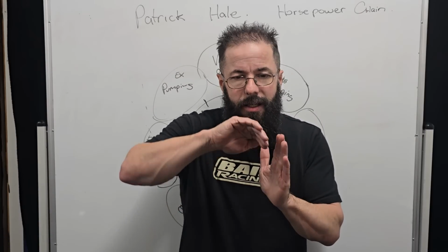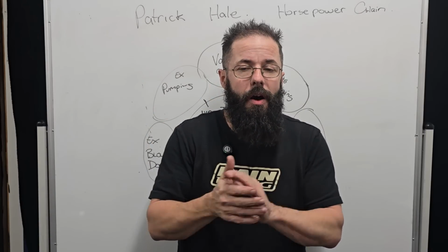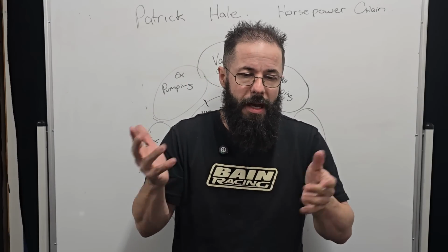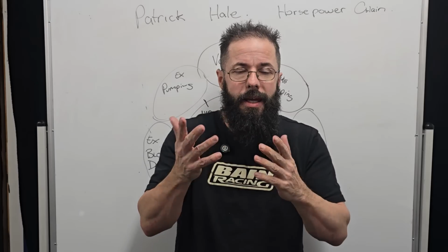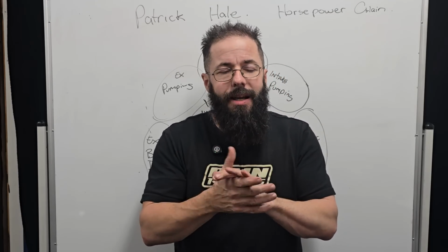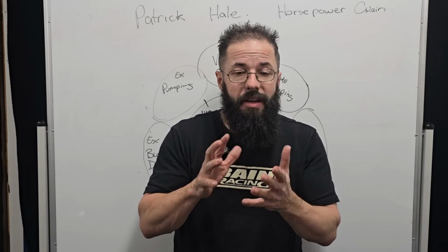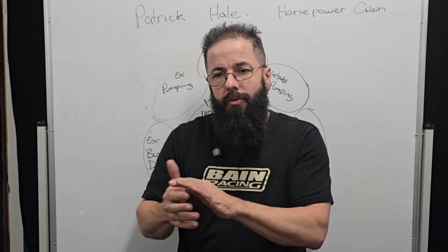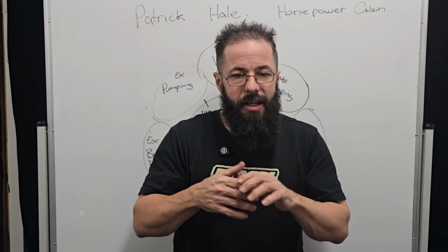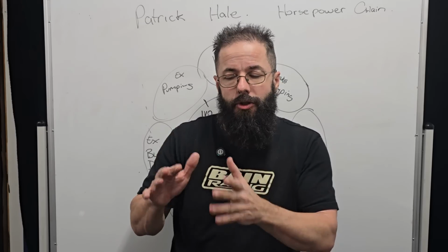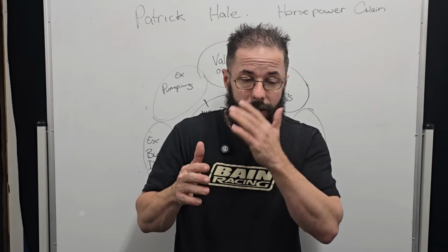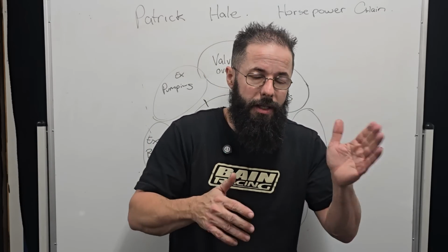And now we're starting to get into asymmetrical profiles. So the front of the ramp isn't the same as the rear of the ramp. And we talked about last week about dual plane camshafts. And some of the math of that has changed. A lot of guys will say anything under 70%, you need to start adding more duration. But with the new chambers that are coming into some of the 2-valve stuff, there doesn't need to be as much exhaust duration compensation. Some of the guys are talking, you know, 8, 10, 12 degrees in the early days.